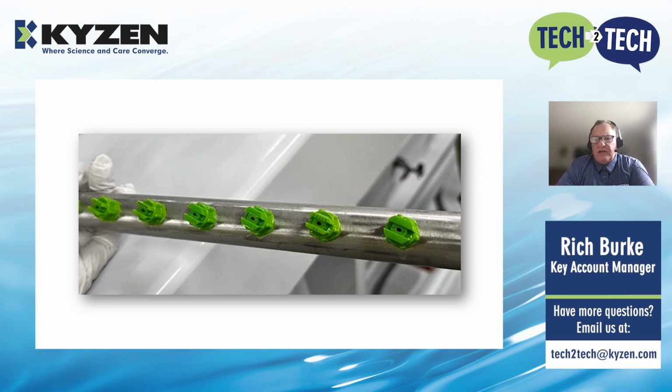Again, these are fan type nozzles. Here's a great picture of what I'm talking about. So you can see very clearly that manifold's out of the machine. The nozzles, you can look at it, they all appear to be clean to us, and they're all positioned with a slight offset, not parallel to the flow of the nozzle manifold itself. So exactly what I'm talking about and how we would want those to be aligned.